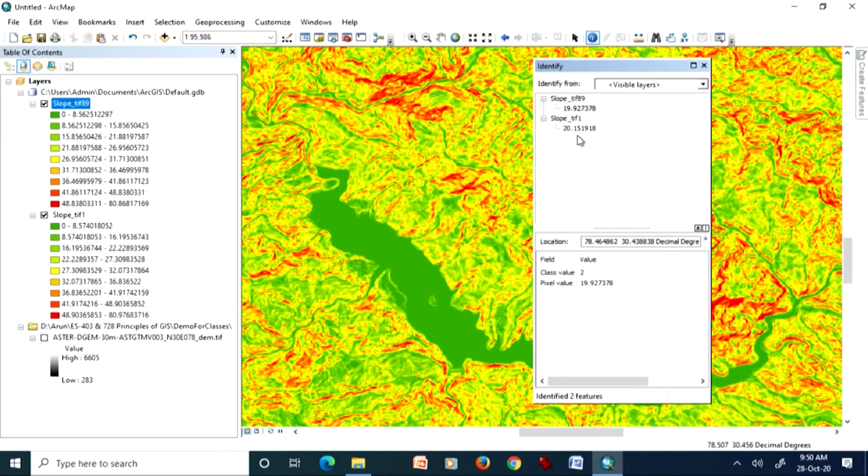So again, when we keep Z factor 1, which is not correct in this case, because latitude and longitude are in decimal degrees, whereas the third axis, that is the Z axis or vertical resolution, here is in meters. So these two are different, whereas in theory we have discussed that Z factor will allow us to convert one to another. So what we are doing, we are converting this height value, which is in meters, to DD by bringing in this Z factor.